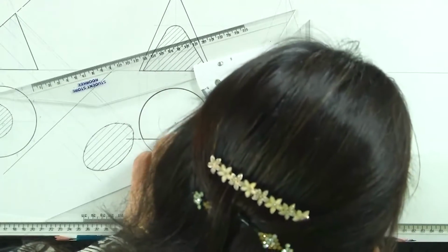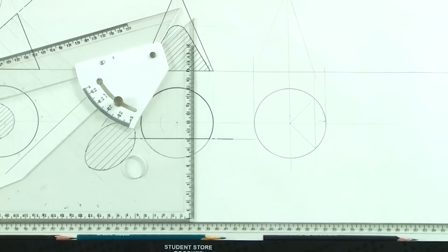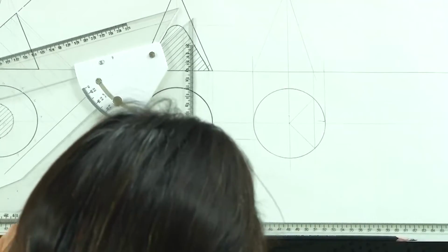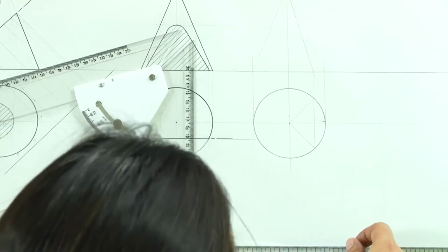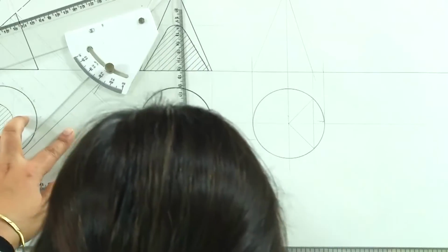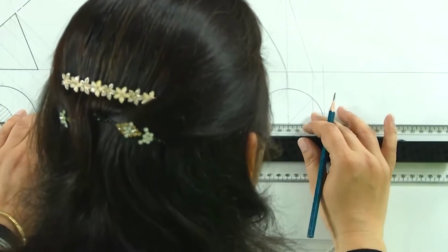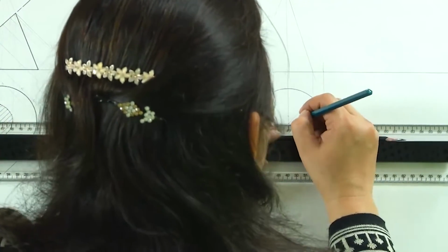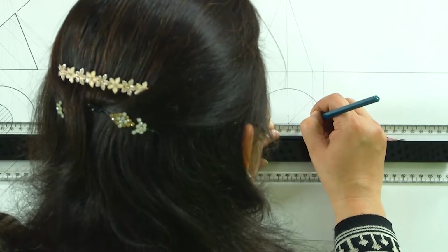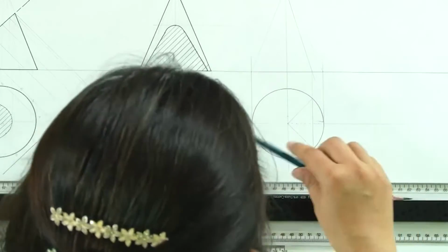So, this is going to be the top view in this case, but what is the true shape of the section for this particular case? For that, we will have to follow the method of concentric circles. Now, what we do in concentric circles is we draw a certain number of concentric circles. So, I am just drawing concentric circles here.